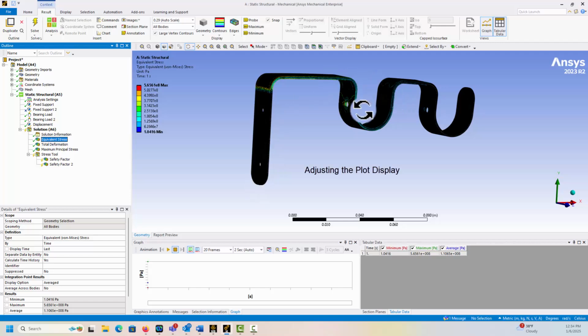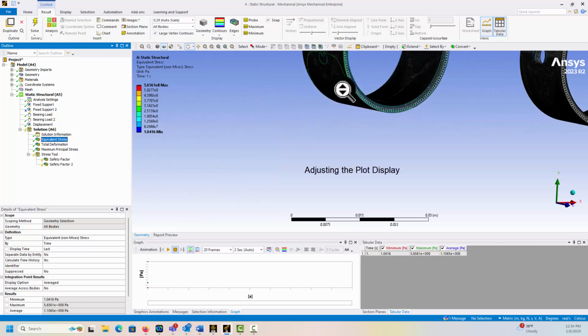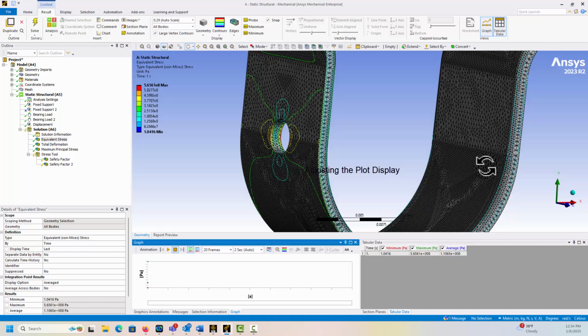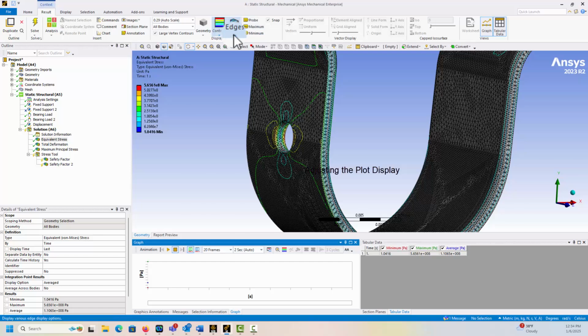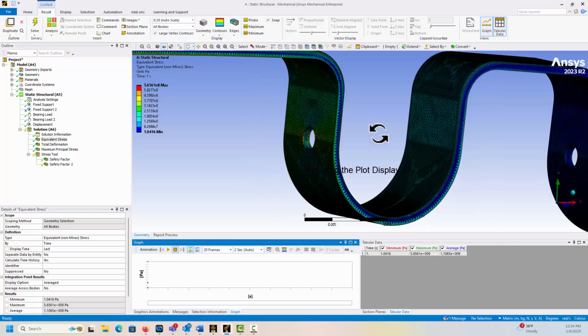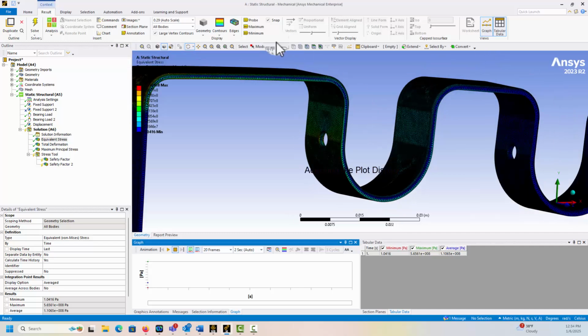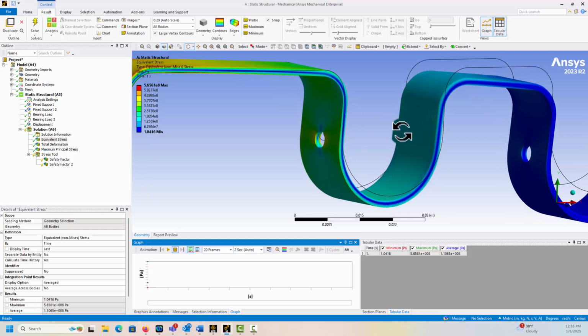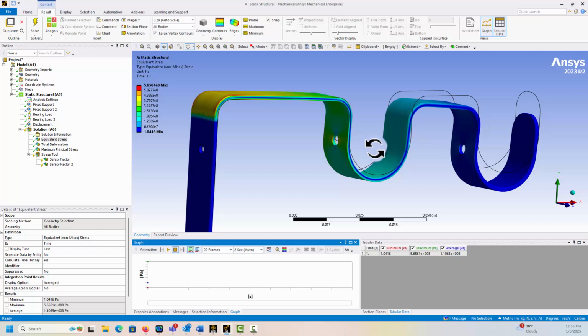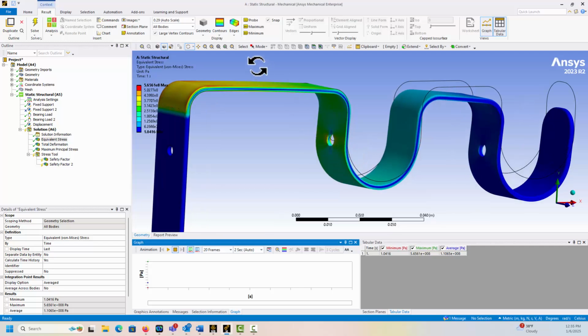We see here it all looks black. If I zoom in, what we're going to see is that's because my mesh is being shown. And we currently have the contours also. We had a different way of showing contours. I can turn off the show elements option here, and I could just show my surface with the undeformed wireframe, which is nice to use as a reference. Now I can see the colors.